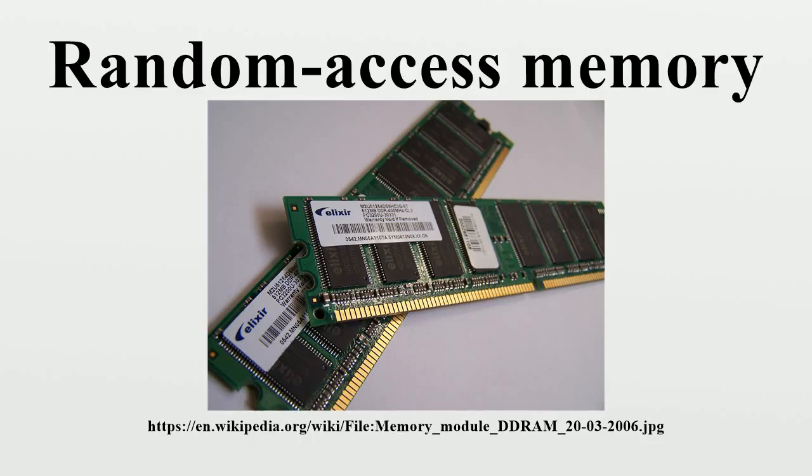Magnetic core memory was invented in 1947 and developed up until the mid-1970s. It became a widespread form of random access memory, relying on an array of magnetized rings. By changing the sense of each ring's magnetization, data could be stored with one bit stored per ring. Since every ring had a combination of address wires to select and read or write it, access to any memory location in any sequence was possible. Magnetic core memory was the standard form of memory system until displaced by solid-state memory in integrated circuits.